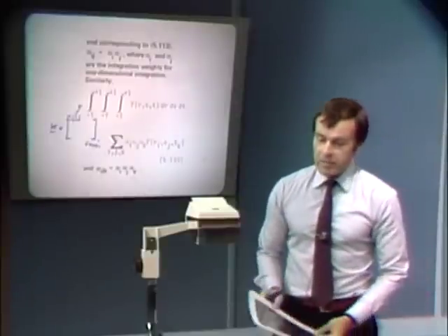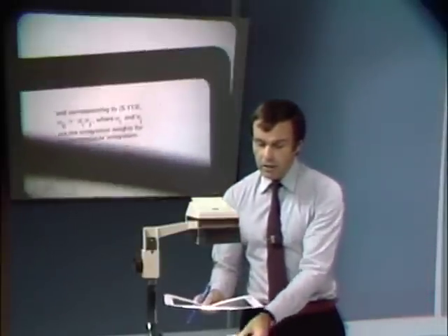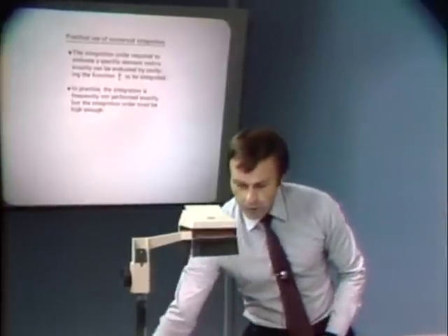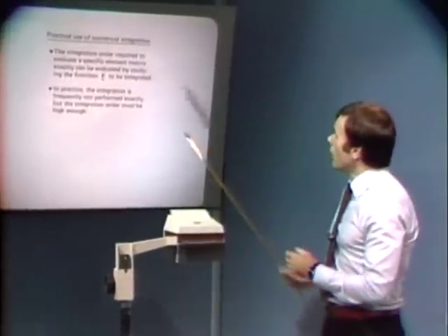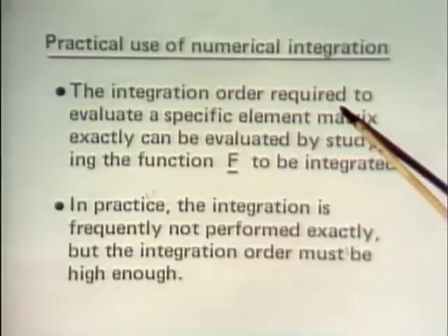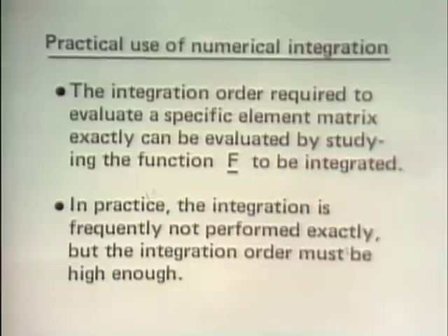Let us now look at the practical use of numerical integration. Well, the first important point is that the order of integration that is required to evaluate a specific element matrix can, of course, be evaluated by studying the function f to be integrated.